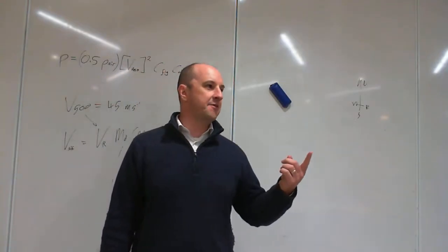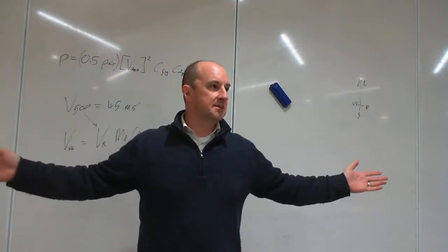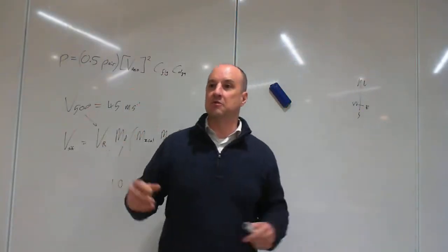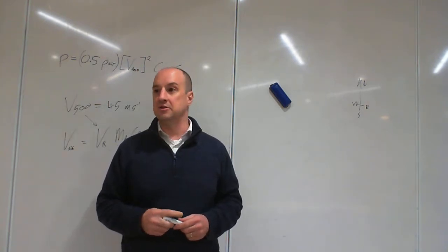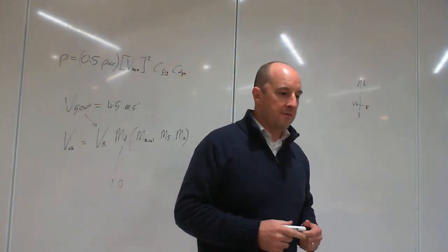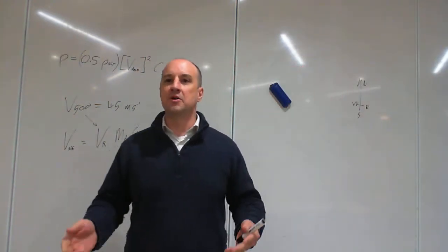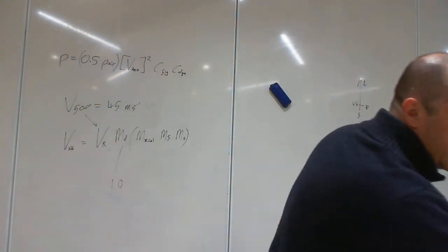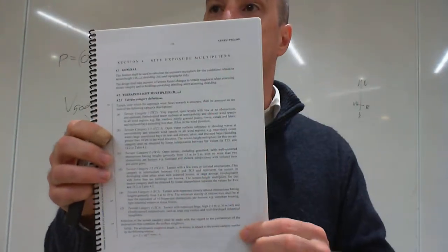So 1 is an airfield where you've got a completely flat area and there's absolutely no resistance to the wind blowing. 4 is in a city, large buildings all around the place, or in a forest, basically lots of resistance to the wind. Okay, and that slows the wind down. If you've got open water, when the wind blows, there are enough waves that actually cause resistance to the wind, so that's category 1.5. And in section 4.2, there's an explanation of what all those categories are.